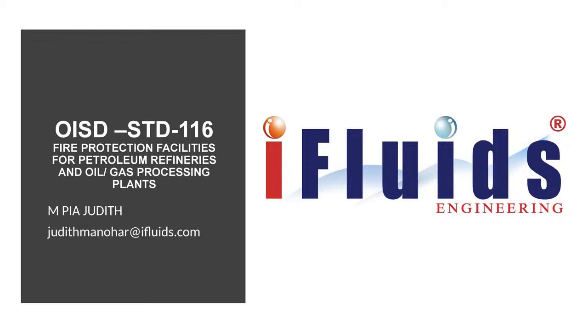Quartzite bulb, what time does it break during fire? For this bulb and detector specification, or the system specification of every system, the OISD itself says that some kind of vendor data has to be procured. So the detailed specification of what exactly has to be provided is not clearly outlined in this OISD. What is outlined is the flow rate, the capacity, the type, and the numbers.